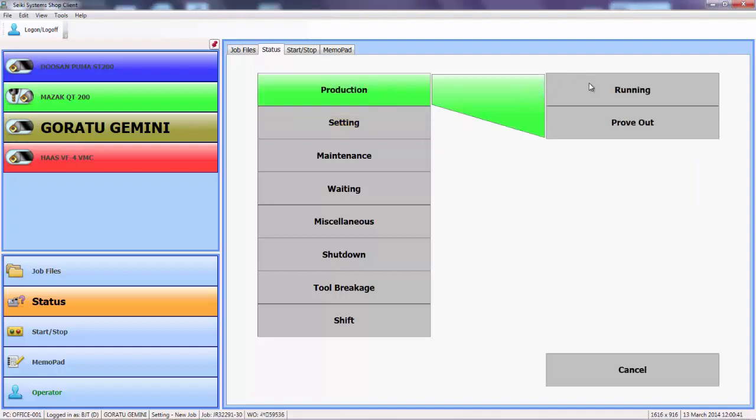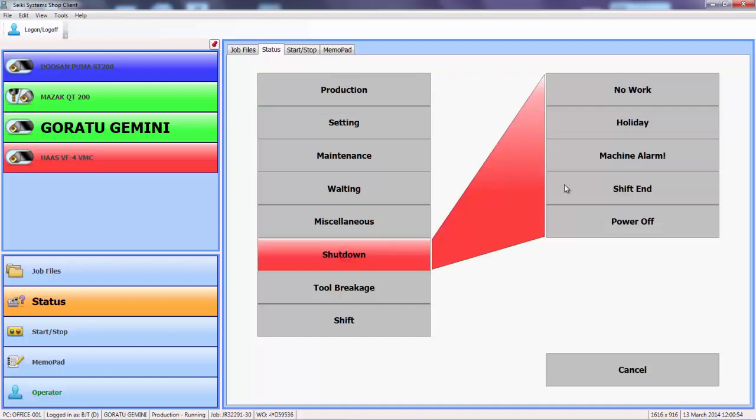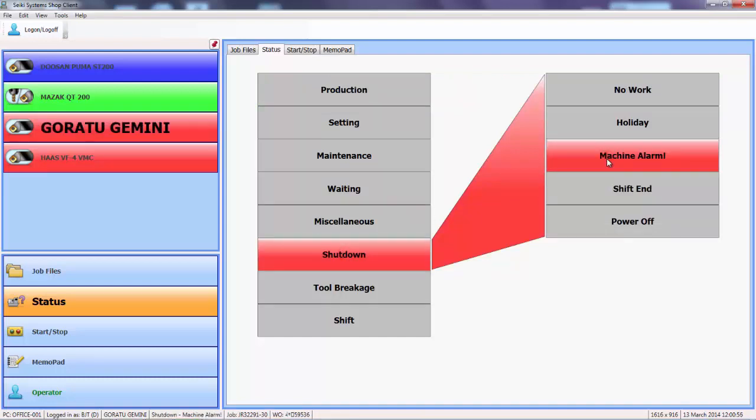When the machine goes into cycle, we will pick that up automatically through a digital input or a direct network connection to the machine, and the same when the machine stops. Depending on the stoppage, we may be able to detect the nature of the stoppage automatically, for example, a machine alarm. In other cases, the reason for the stoppage is supplemented with input from the operator.